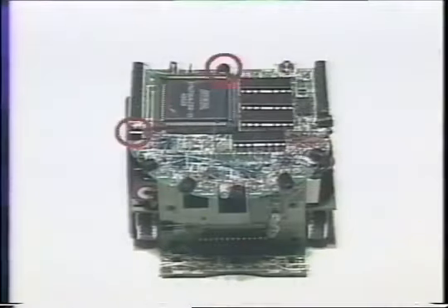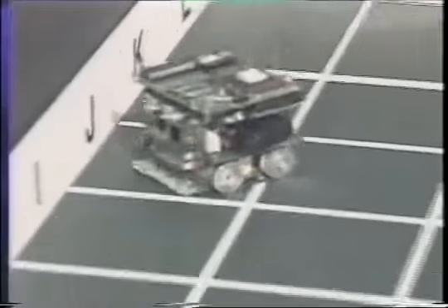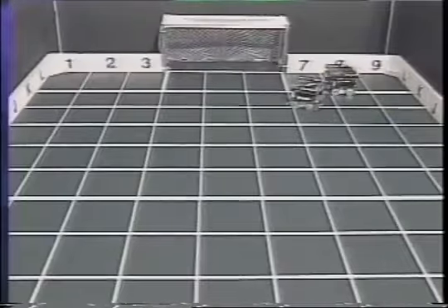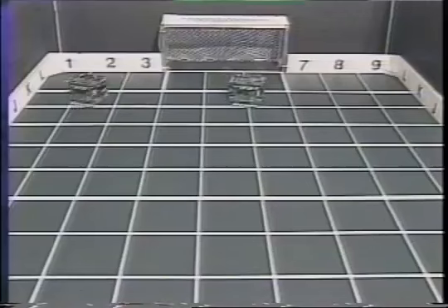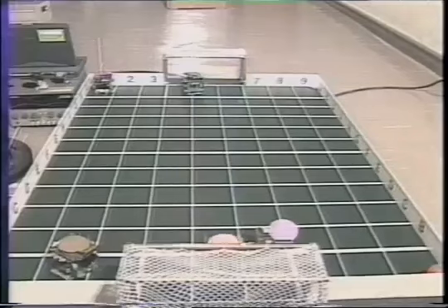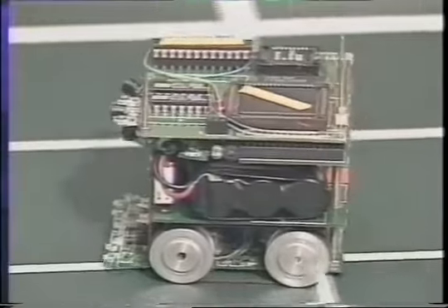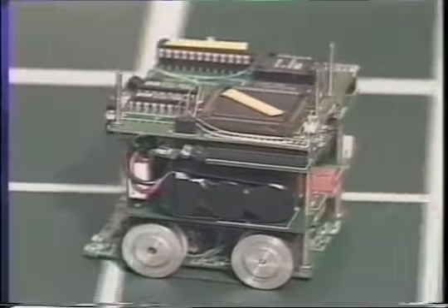8 infrared sensors for perceiving obstacles around can detect the distance in 3 different steps: close, far, and very far. They are deliberately designed so as not to be sensitive to the external light condition. The other 8 infrared sensors under the body detect white lines on the field so that the robot corrects its accumulated position and orientation errors.